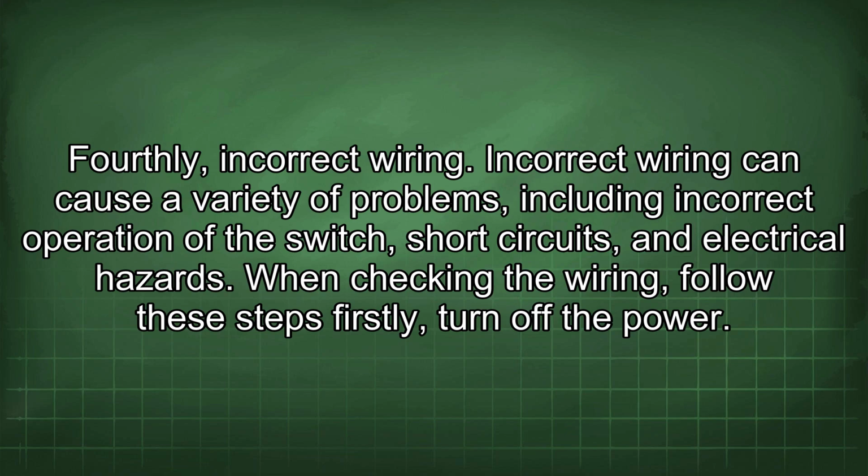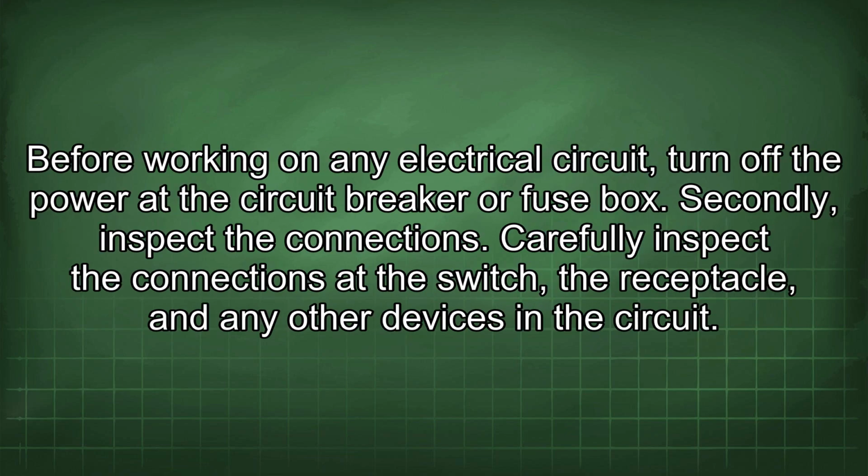Firstly, turn off the power. Before working on any electrical circuit, turn off the power at the circuit breaker or fuse box. Secondly, inspect the connections. Carefully inspect the connections at the switch, the receptacle, and any other devices in the circuit.